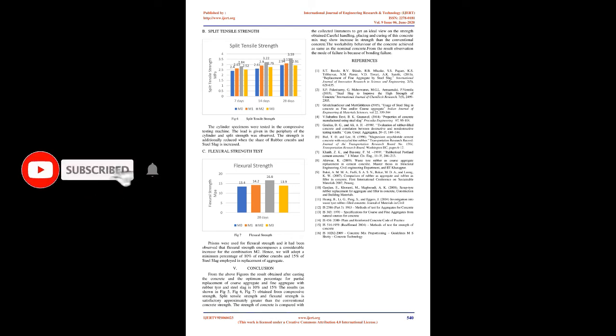The cube specimens were tested in a compressive testing machine, and the compressive strength of concrete was observed that the strength was decreased with an increase in the percentage of rubber crumbs and steel slag. Hence, we can adopt a minimum percentage of 10% of rubber crumbs and 15% of steel slag utilized in replacement of aggregate. B. Split tensile strength. The cylinder specimens were tested in the compressive testing machine. The load is given in the periphery of the cylinder and split strength was observed. The strength is additionally reduced when the share of rubber crumbs and steel slag is increased.